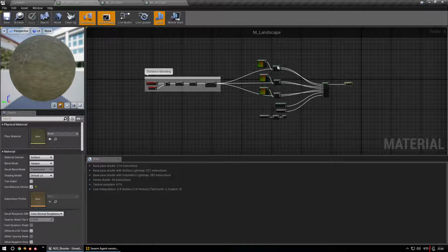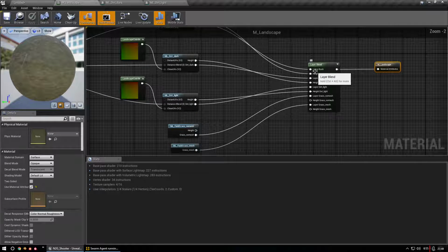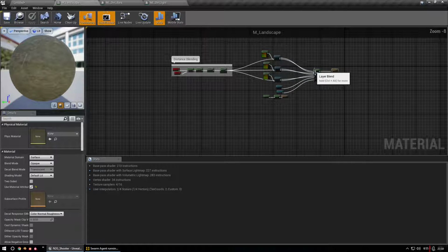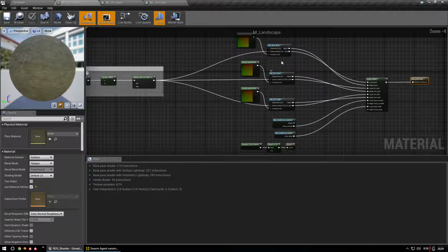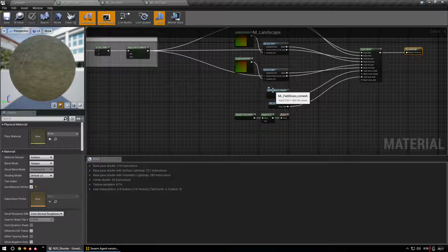That limits the layers. Technically I can add as many layers as I want, so I'm unlimited there, but I'm limited to a total texture count of 32, according to Epic. But what we want to look at is 16. I'm not pushing past 16, and definitely haven't with this. I think I have 2 in this one, 2 in this one, 2 in this one. These 2 are the same, so it just counts as 4. The grass I think is 4 a pop, but these are 2 mirrored grasses with no difference in them whatsoever.